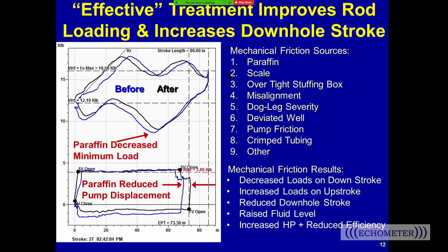If you have a big pump, you can cause excessive under travel by putting in too big of a pump, or putting a fiberglass rod string in and going slow with a big pump, or a rod string that's small that can stretch. So all of those can cause it.